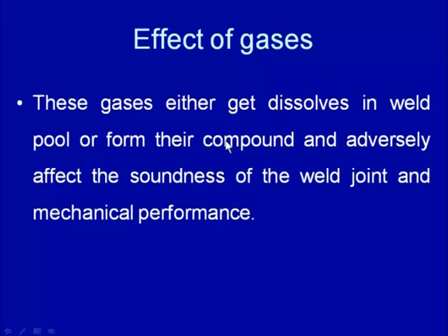One common way is that these gases, because of their high solubility in the molten metal, get dissolved in the weld pool, and if enough time is not given for these gases to come out of the weld pool during solidification, they can get entrapped in the weld pool and produce gaseous defects in the weld joint.